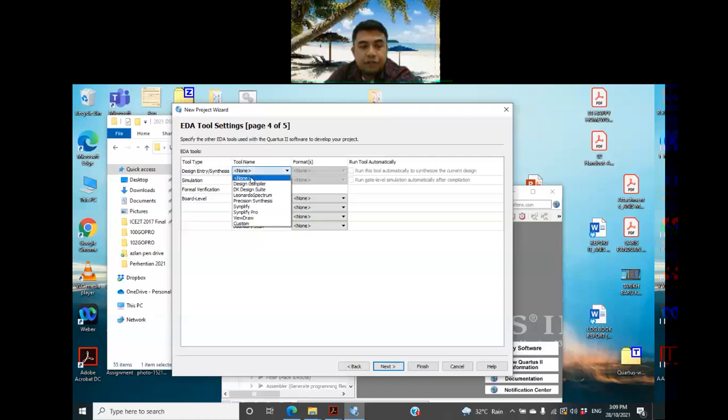So you have design entry. This one, I think should be none. Simulation, you take ModelSim Altera, and you take Verilog HDL. Remember that yesterday I told you about Verilog and VHDL? So we use Verilog HDL.